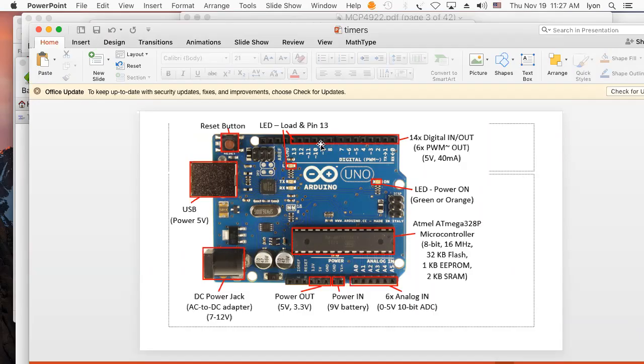And if you're ever wondering, you could always just use a continuity checker and make sure. Sometimes we have new hardware coming into the lab and we don't know how it's set up. I always encourage people to check how things are wired, especially since you're coming up with shields that may be made by third-party vendors who are selling on eBay for as cheap as they possibly can.